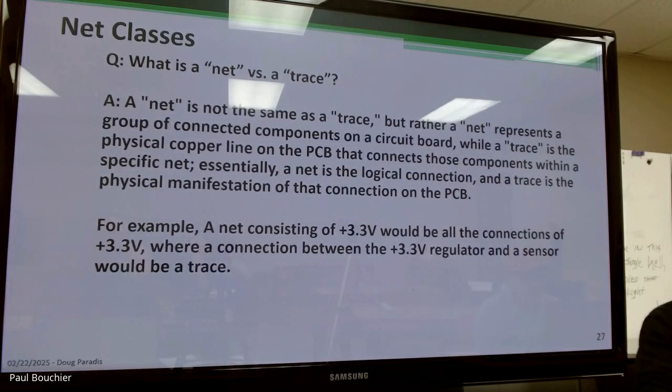So here comes the big rub. We have a good example here of where the connector goes into the power regulators, which is connected to ground. So I have design rules for the ground net class, or the ground net. Right now, because we haven't changed anything, it's going to be the default design rules. Would I really want the battery power line to be the minimum trace of 0.01 something? No, probably not. But it's part of the ground plane.